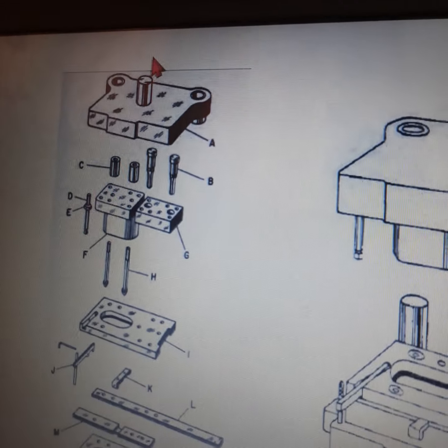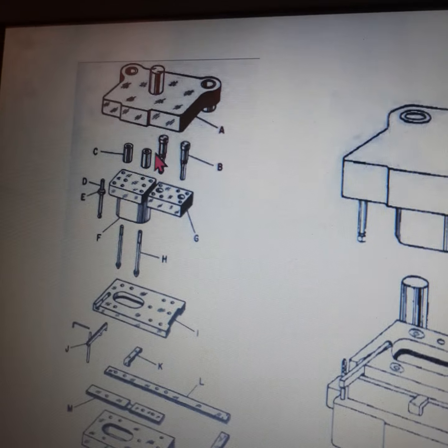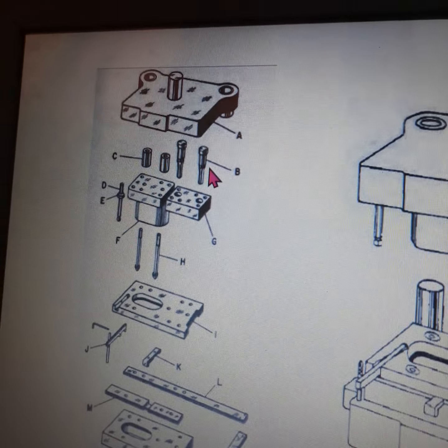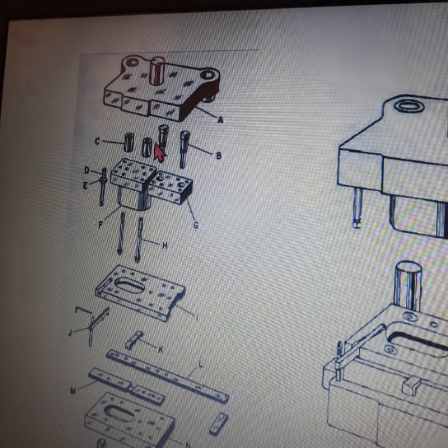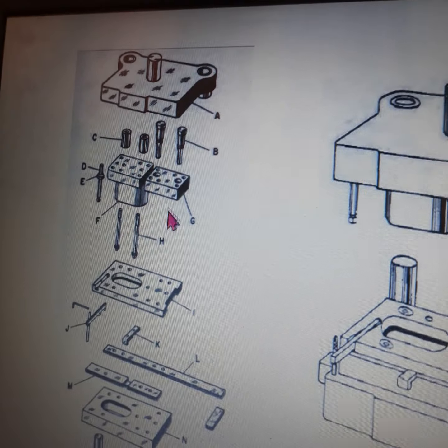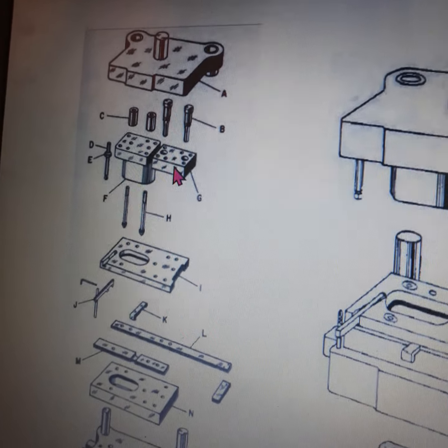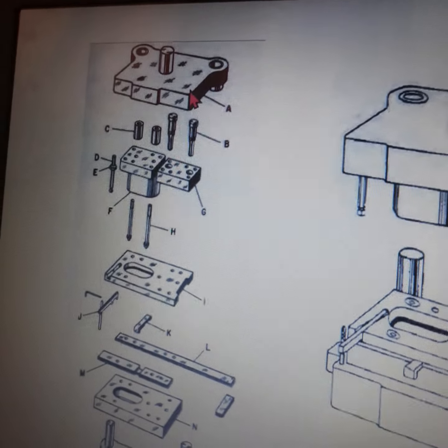On the top die shoe we are going to mount the piercing punches, two in number. These two piercing punches, being smaller in size, cannot be directly mounted to the top die shoe. So we first hold these two piercing punches onto a punch plate. This is the punch plate. This punch plate in turn can be mounted onto the bottom surface of the top die shoe.